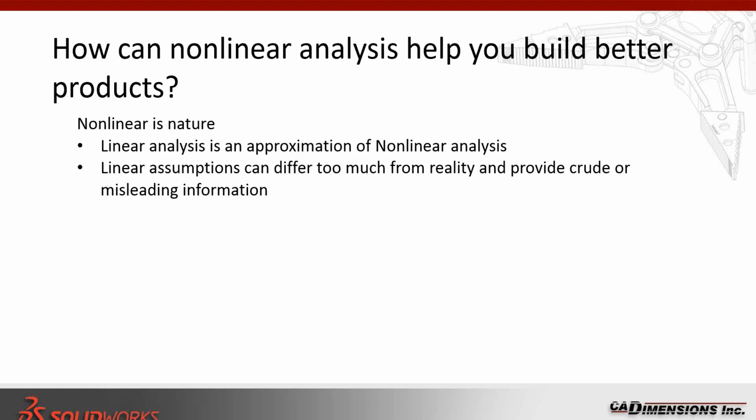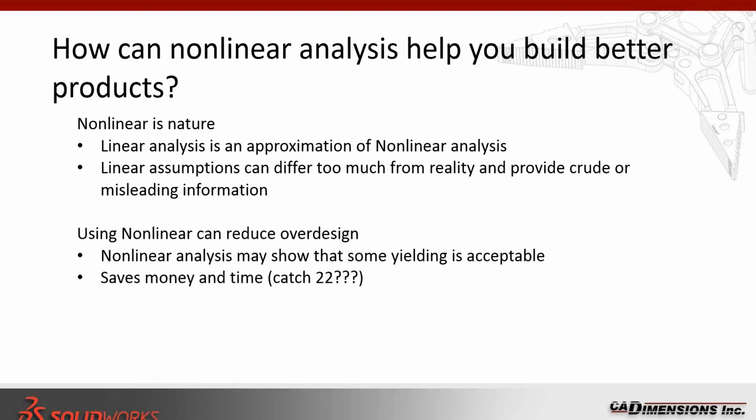Of course, if your linear assumptions differ too much from reality, you can get misleading information. It might say your part is failing when it's not failing. Using nonlinear can reduce over-design. So nonlinear analysis may show that some yielding is acceptable.